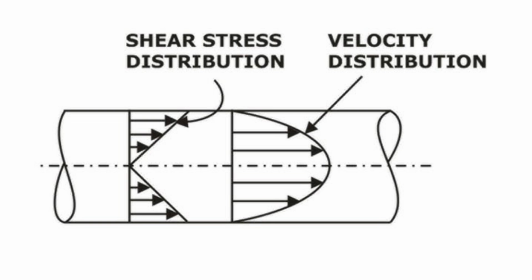So now let us see contour visualization. To better visualize this, let's generate contour plots. This will show how velocity and shear stress are distributed inside the pipe cross section. You will see that the velocity is highest at the center and gradually decreases toward the walls, forming a smooth parabola. Similarly, shear stress is 0 at the center and increases towards the pipe wall.